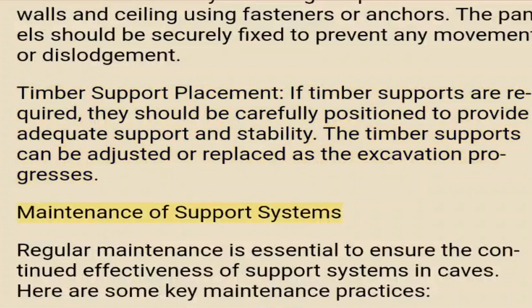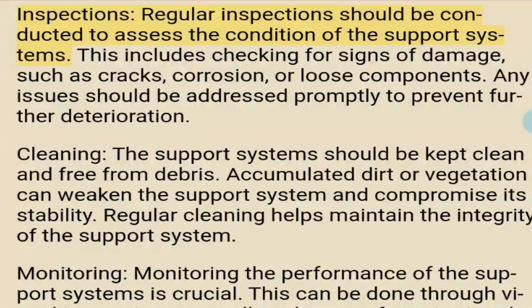Maintenance of support systems. Regular maintenance is essential to ensure the continued effectiveness of support systems in caves. Here are some key maintenance practices. Inspections. Regular inspections should be conducted to assess the condition of the support systems. This includes checking for signs of damage, such as cracks, corrosion, or loose components. Any issues should be addressed promptly to prevent further deterioration.